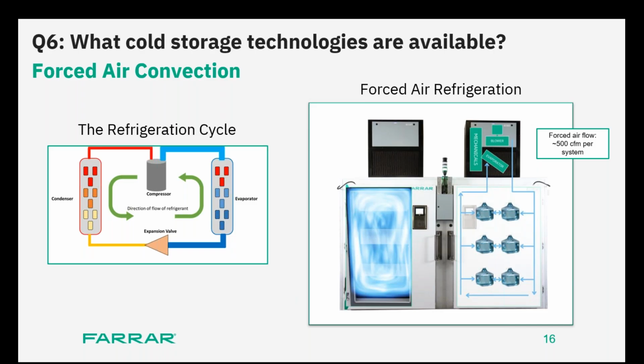And that's highly critical because when you're looking at bioformulation or drug products, freezing your sample faster would always create smaller ice crystals. And that's critical because smaller ice crystals maintain the integrity of your samples. If the ice crystals get larger, they would penetrate the cell membrane. And once you thaw the samples, a lot of them will be destroyed. So forced air convection really helps you with that.